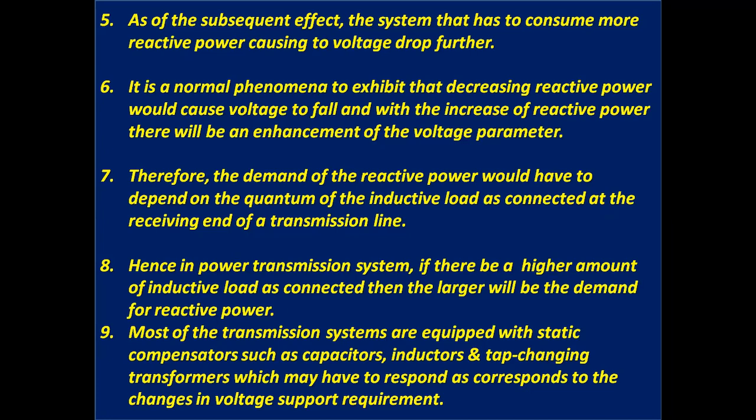Again, I repeat, it is a normal phenomenon that decreasing reactive power causes voltage to fall, and with an increase of reactive power, there is an enhancement of the voltage. Hence, in a power transmission system, if there is a higher amount of inductive load compared to capacitive load, then the larger will be the demand for reactive power.